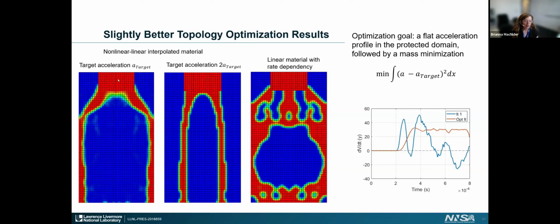And this is an additional step to help with the stable time step. One of the things that we were running into was that in some of our simulations, the very, very soft elements can deform a lot. And if they are also nonlinear, then you can end up in a situation in which the local stiffness sort of spikes because of the material model. So it helps a little bit to have the soft material be linear to avoid those stability issues.